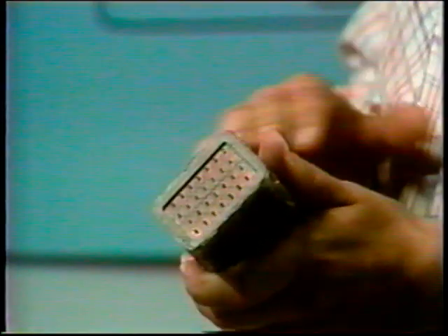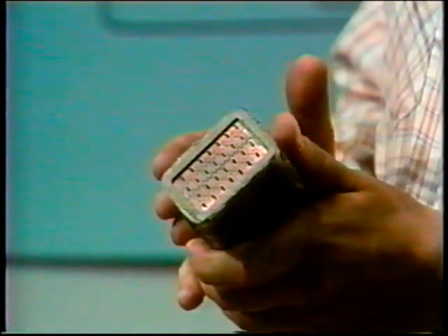Now, let's move on to the third auxiliary system that's sometimes used in large AC generators. This system cools the generator by forcing water through the generator's stator windings. The stator windings in a large AC generator are made of bars. Now, this is a piece of bar from a generator's winding. Around the outside of this bar is an insulating material.